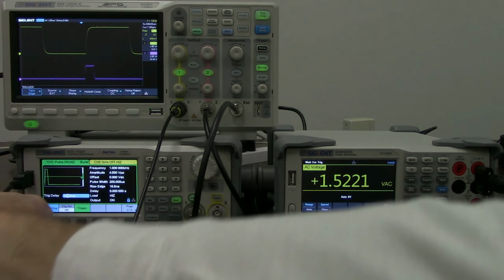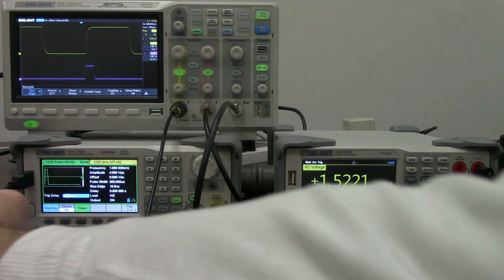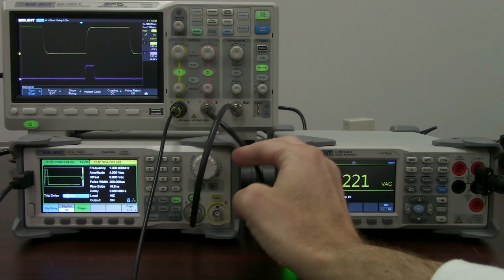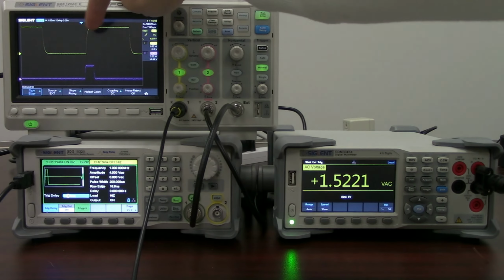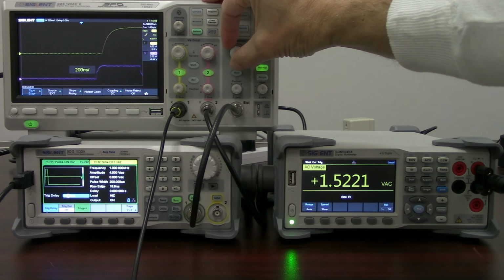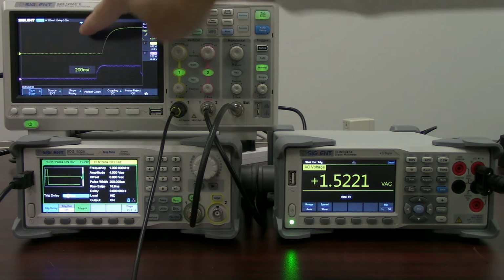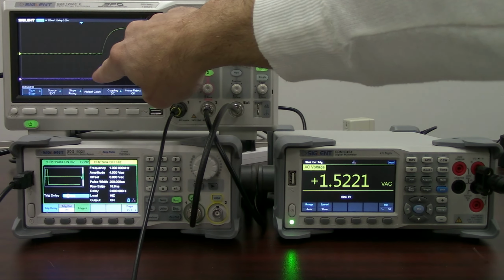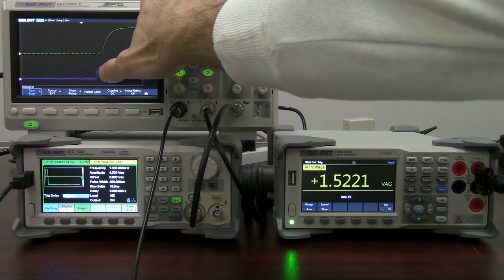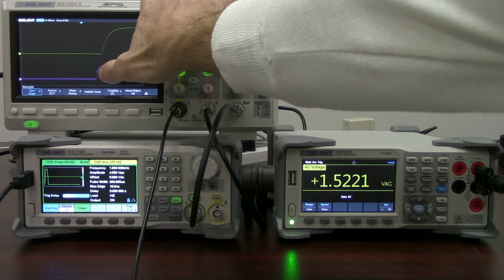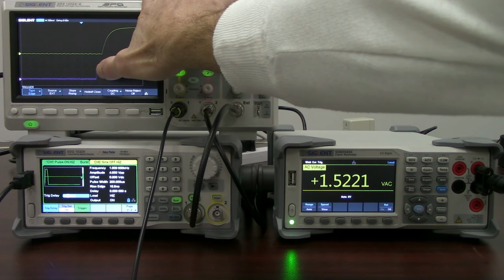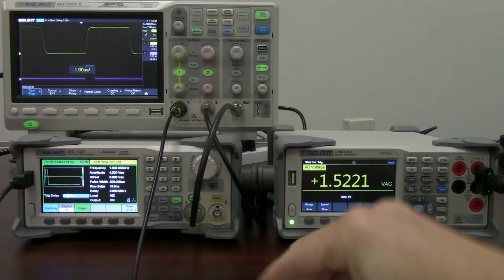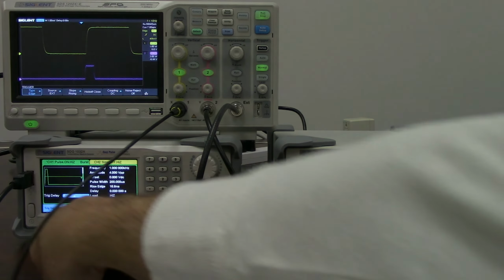So the yellow trace is channel 1. You'll see when I have a square wave, that's coming off of a demo board that I have here. And then we're measuring the actual trigger output from the back of the oscilloscope. You can get an idea of some of the delay here. So here is our trigger point, and we're at 200 nanoseconds per division. So we're at about, I'd say, 350, maybe 375 nanoseconds of delay. So that is something that you're going to want to keep in mind when you're making those measurements.